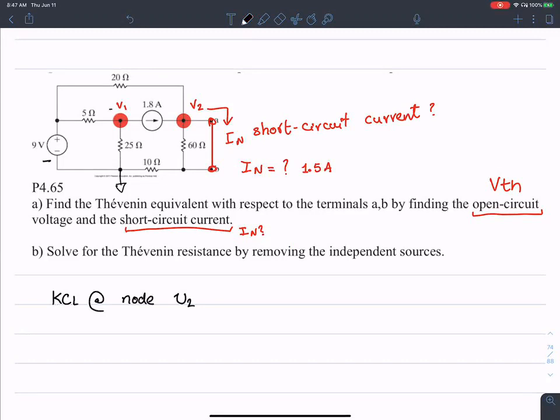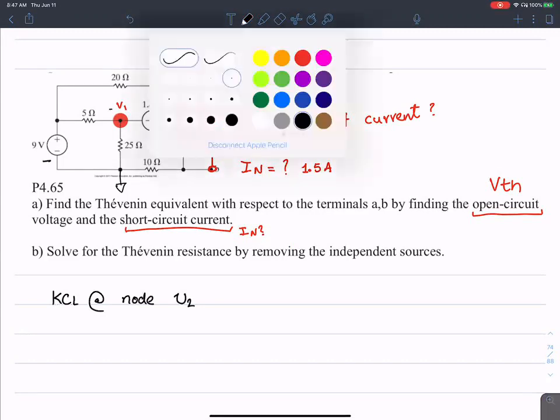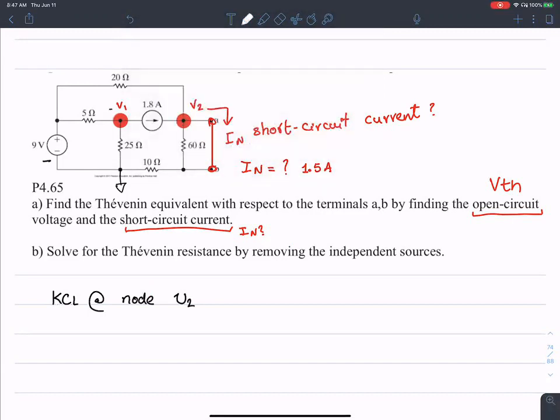The first thing we want to recognize is that this guy is not present in the circuit anymore, because it is short circuited with a parallel 0 ohms path, right? So questions about that? The first thing I'm going to do is to remove this part from the circuit. That's because I short circuited using a parallel path just to the right of it.